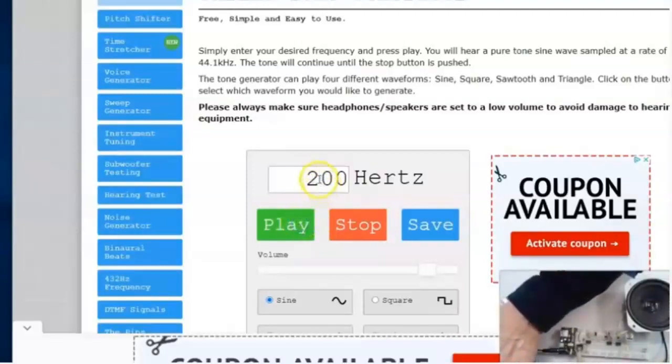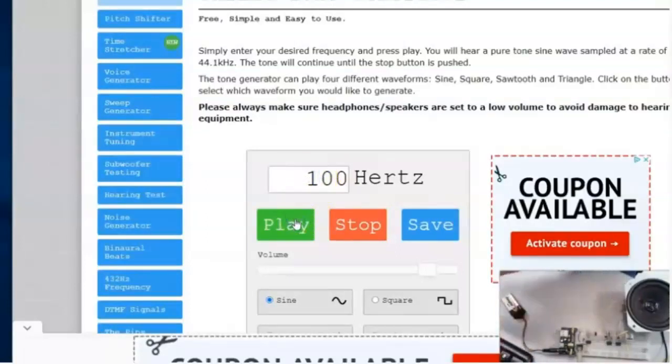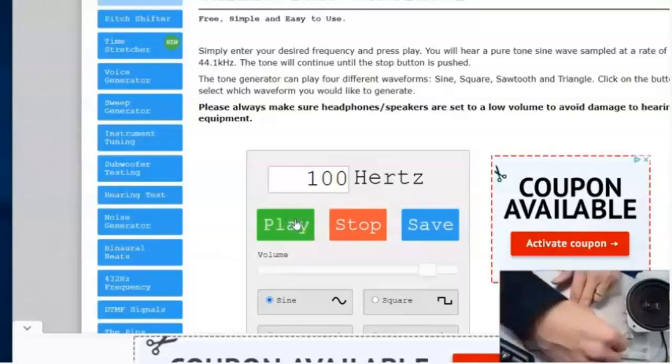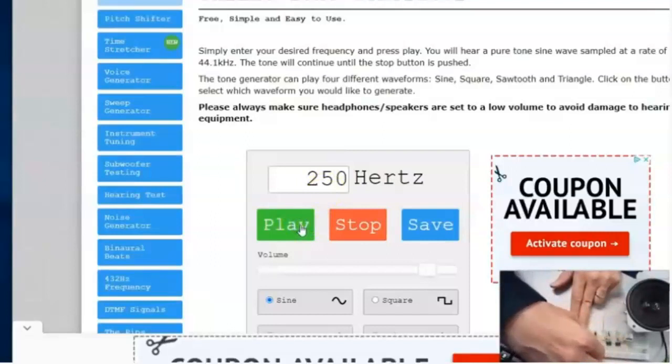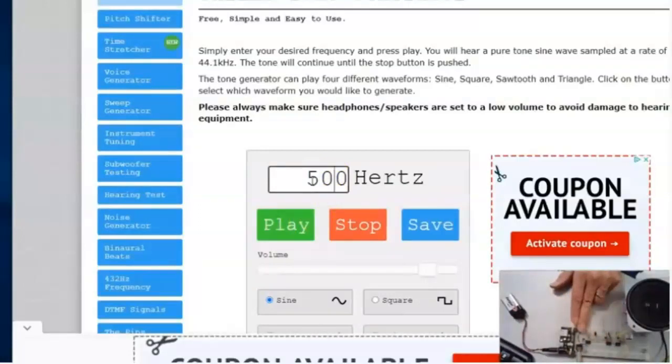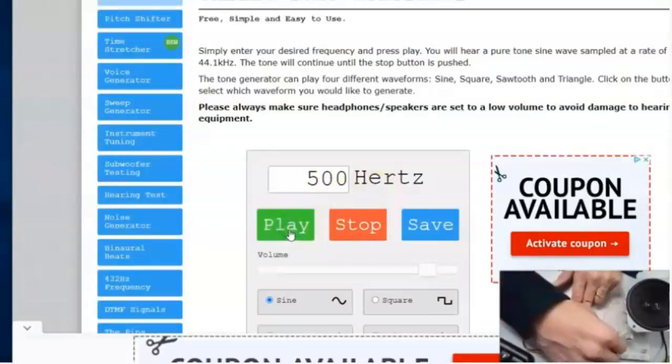Running through the filter, it's blocking 800 hertz, going down to 400, 200, 100. And at 100 hertz, this is the output of the filter, input of the filter. Basically the same, a little bit louder because the filter adds a little bit of gain at DC. At the corner, it's 250 hertz, with a filter, without a filter, and 500 hertz. After the filter, without the filter, with a filter, without a filter. If we put that on a voltmeter, you can actually get some numbers.